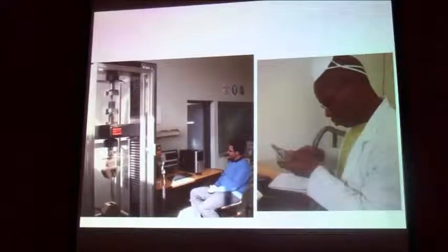Over here we can do something about the driving forces, and we'll talk about that later, because you are driving it yourself. You're choosing how big to make your excavation, and then what sequence to make it, and how to support it. But a lot of what we do, working with our rock engineers and mining engineering colleagues, is working together and advising how to make your excavation safer.